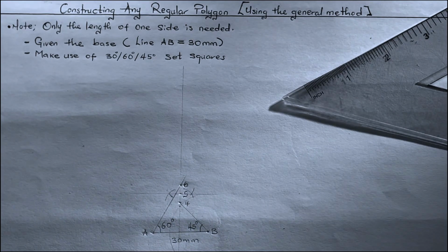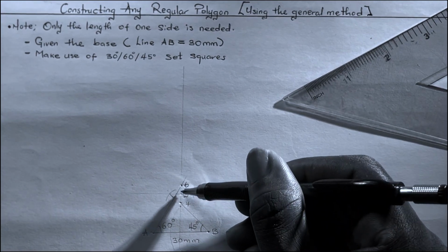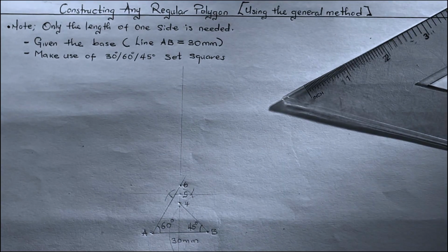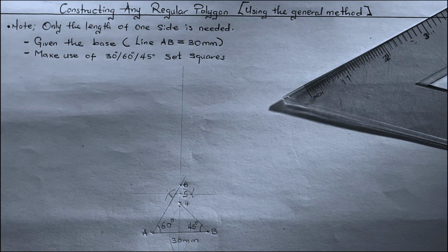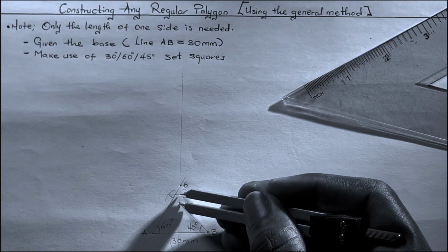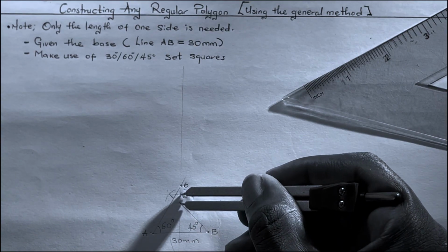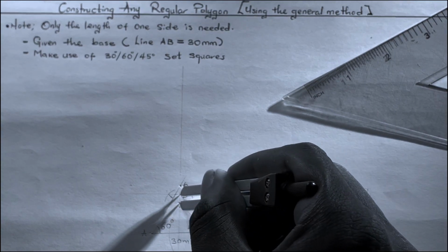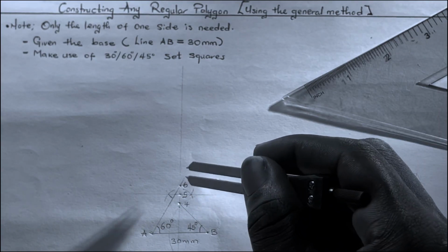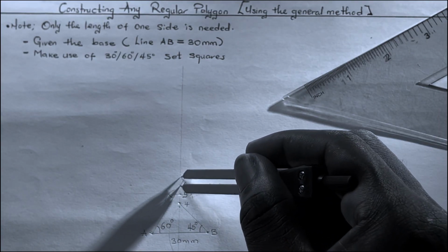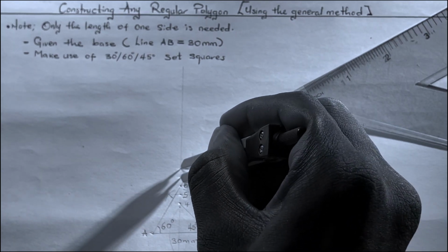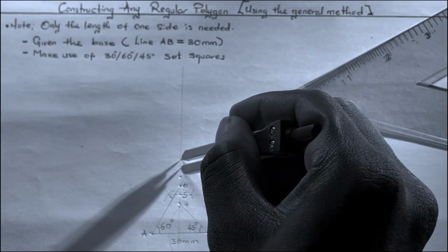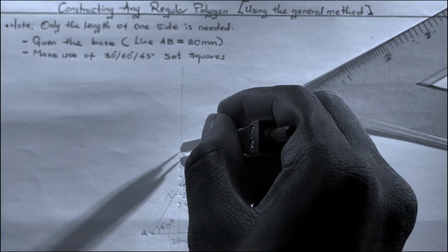So to extend this equidistance upward, we're going to be making use of our divider to transfer the length of each of the sides. The distance between 4 and 5 is observed to be this. So we extend those points upwards to have our point 7, point 8, point 9, point 10.